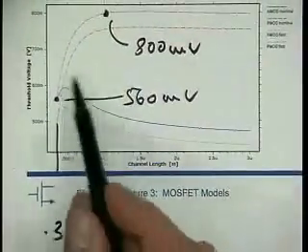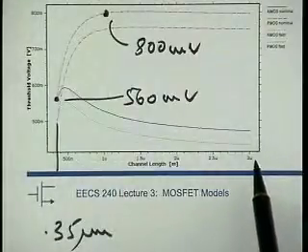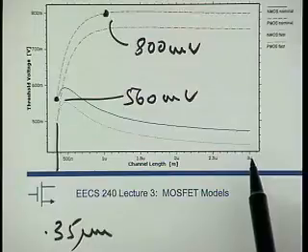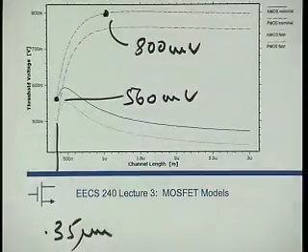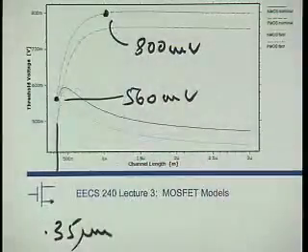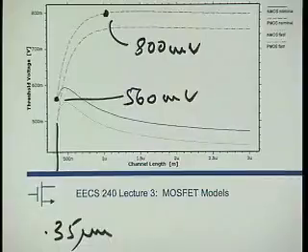And the funny thing is that the PMOS device behaves completely different. In fact, the PMOS device, so that's the opposite, right? And that's a further complication, right? This idea that the threshold voltage should drop as the channel length gets smaller, that comes out of textbook calculation.